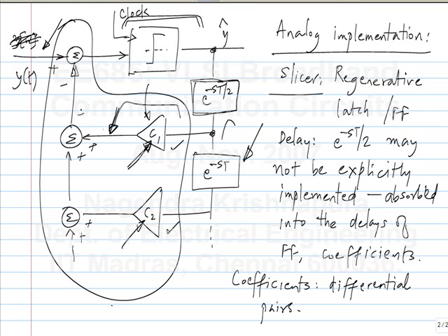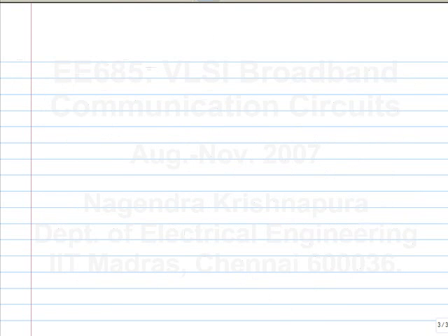Now, these will be implemented using D flip-flops, because it is one period with respect to the previous one. Depending on how many values you have for the coefficient, what is implemented is, in a way, a selector. To implement the coefficients in the transmit equalizer, what we did was to vary the tail current. So you select the tail current, that's essentially what it is.